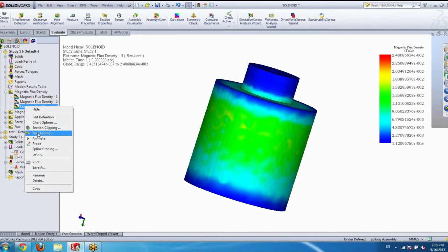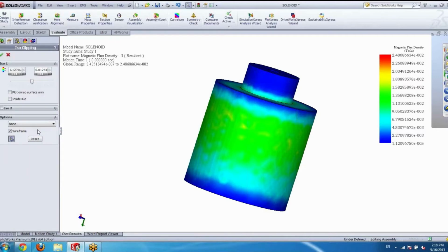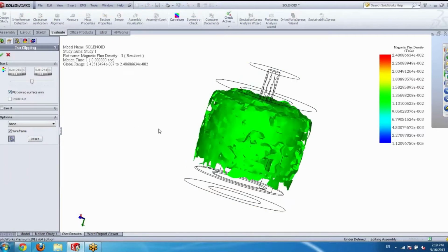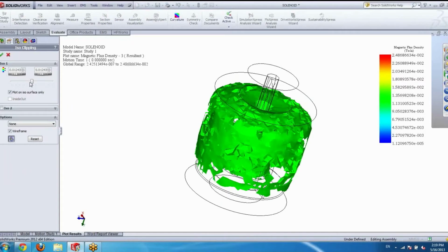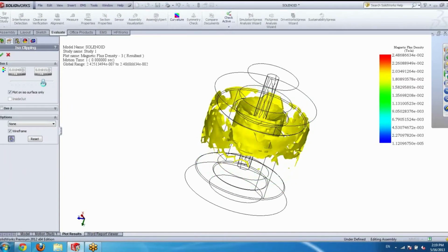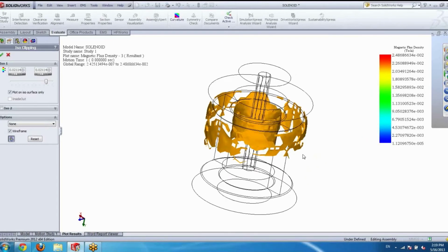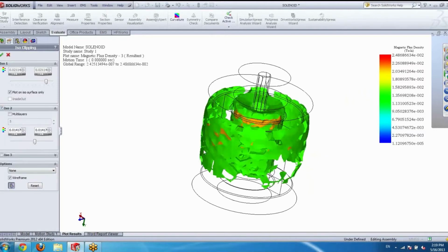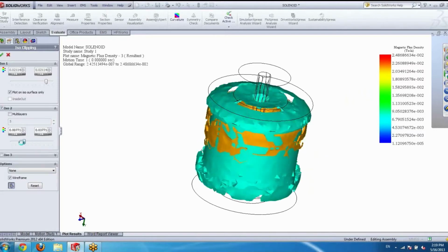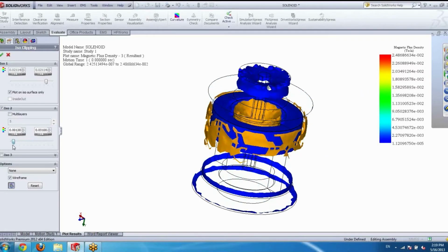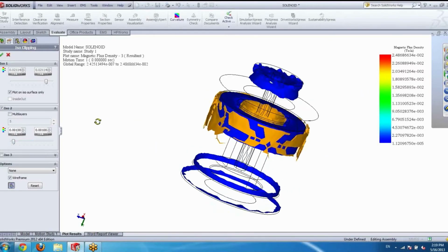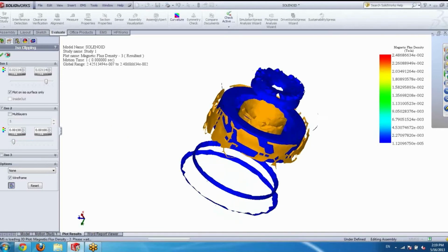Also, you can also do an ISO clipping plot. Basically, ISO clipping is going to bring all the spots in your structure that have the same value. You can specify that value using this cursor right here. So all the spots that have, for instance here, 0.0211 are right there in my plot. This is very handy when you're looking for minimums and maximums. Again, you can superimpose up to 6 ISO clipping surfaces there, so there's no limit in that regard.